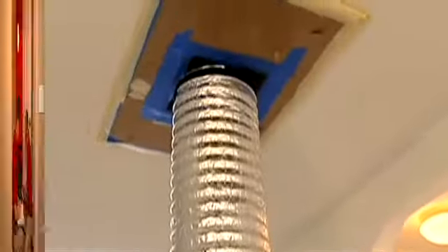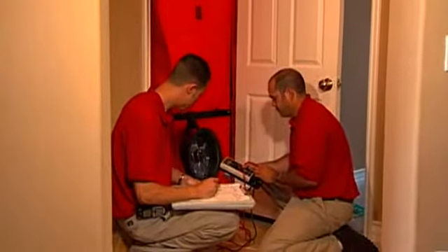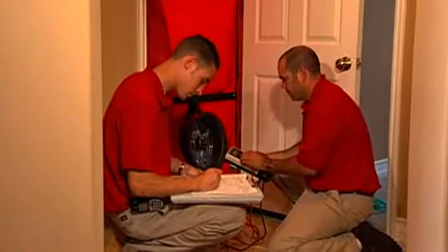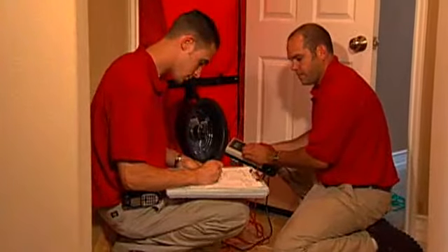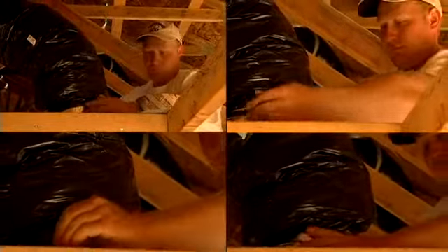it is often cost-effective to run it at the same time you're testing the airtightness of the building envelope with the blower door. The downfall, of course, is that if the test fails, it's difficult to make corrections. The remedy, of course, is to be careful and precise with duct sealing to begin with. Of course, the easiest of all is to bring all the ducts inside the building envelope. In this case, duct tightness testing is not required at all.